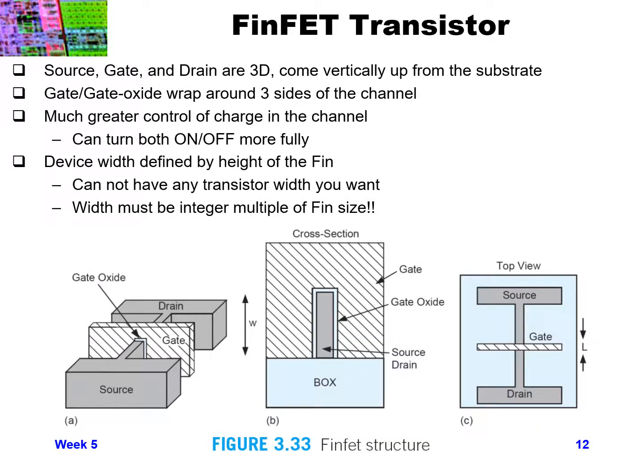One of the biggest process enhancements to silicon CMOS process in the last few years has been the FinFET transistor. Up until now, whenever I've shown a MOS device, you have the silicon surface of a wafer, and the N+ diffusion, the channel, and the N+ diffusion for an NPN transistor are all at the surface of the wafer, and it's a flat silicon surface.